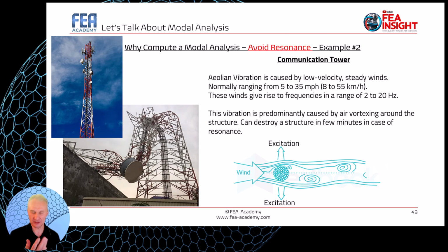Okay, where does it come from? It comes from a vortex effect. So you see on the picture here, you have the tower. We see the tower from the top. Okay, and you have the transverse wind here like that, and the tower creates a separation of the wind. Here behind the tower there is a vortex effect,